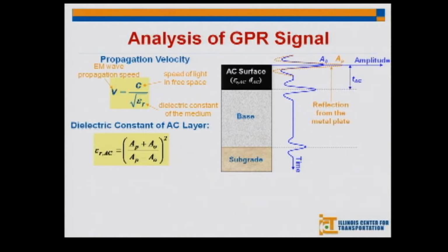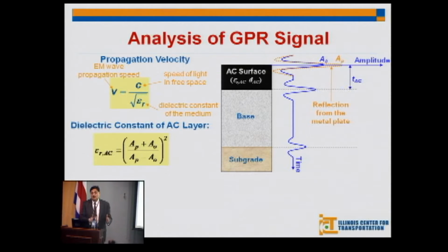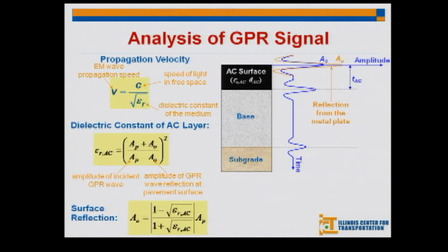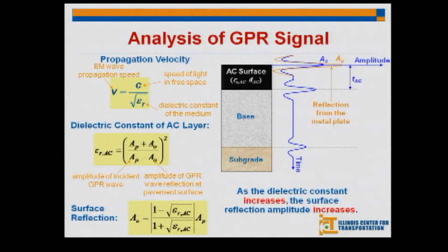If the pavement is new, that's fine. If the pavement is old, then you have to know that there is an error in what we are doing. That's what is usually used by people who are trying to determine the thickness; they usually use the reflection just from the surface. So if the surface is aged, the dielectric constant is going to be different than what's underneath the surface. So from that also, the surface reflections will be able to calculate the dielectric constant.